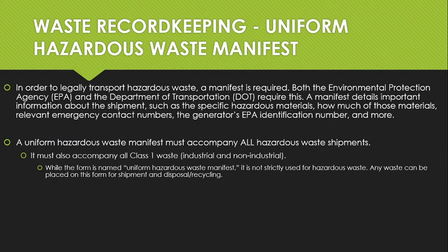So, like I said, you can see it here. In order to legally transport hazardous waste, a manifest is required. This is required by the EPA and by DOT. So any hazardous waste manifest has to accompany all hazardous waste shipments. It also has to accompany any Class 1 waste. So if you've got an industrial facility and we're picking up Class 1 waste,